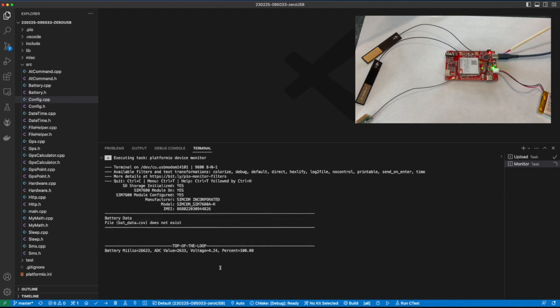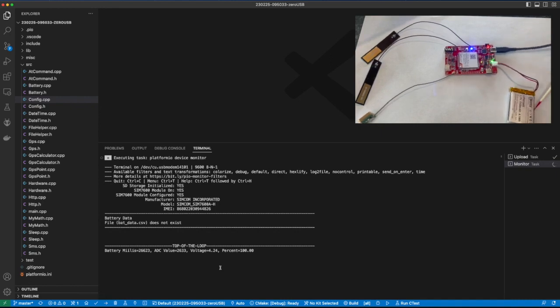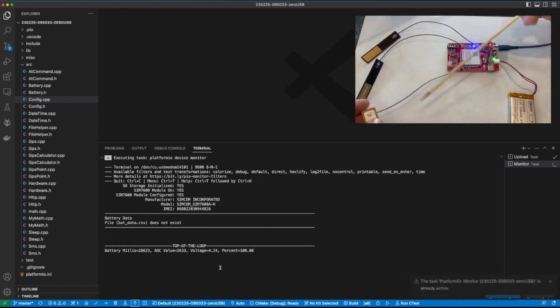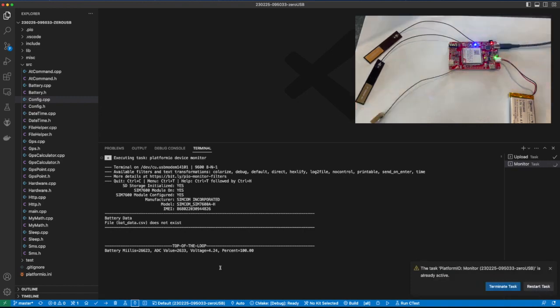I'm programming this and powering it through this USB-C port. And then it also has a battery plug right here. So standard battery plug, you can see this battery, push it in. This is the battery I've tested, and you can plug other batteries into this too. When the USB-C port is plugged in, it does charge this battery, and we'll see that in a little bit. Antenna-wise, this is the GPS antenna, the standard square GPS antenna over here. And you can see the two LTE antennas here. There's one as a primary, I forget which one's primary, which one's secondary, but the two antennas are there.